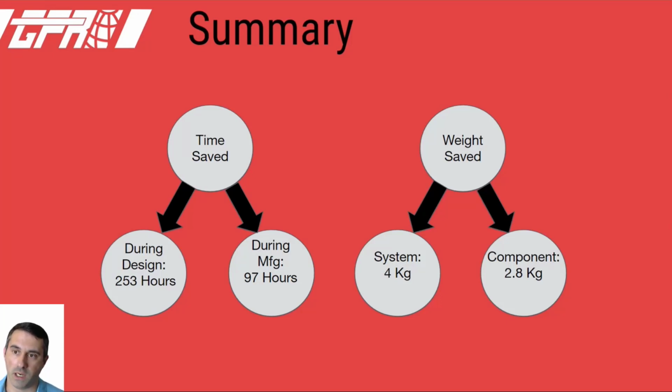The other thing to consider is Star CCM Plus has something built into it called the Design Manager, and that allows you to do a lot of the stuff that I see teams want to do with automating design exploration. You can give it exposed CAD parameters and say, hey, I want you to go do a sweep or an optimization case or whatever it is. Here's all the data I want. Here's the scenes I want. Go run 20 cases, 100, 200 cases, whatever it is.